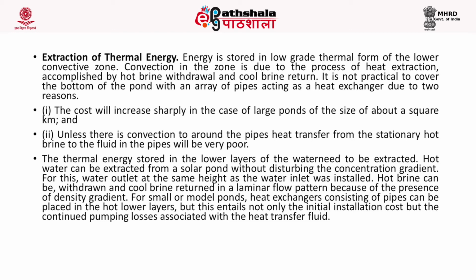acting as a heat exchanger, because the cost will increase sharply in the case of large ponds, to the size of about a square kilometer. Unless there is convection around the pipes, the heat transfer from the stationary hot brine to the fluid in the pipes will be very poor. So it is not practical to cover the bottom of the pond with these pipes.